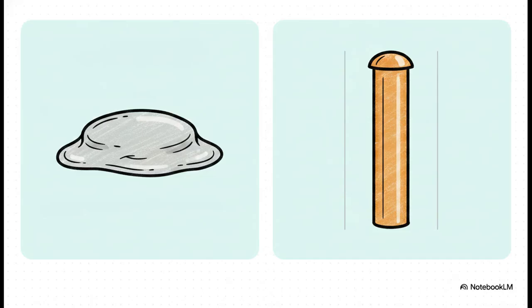To fix this, engineers execute a brilliant structural upgrade. They swap out squishy, fully melting traditional solder bumps for rigid copper pillar bumps. These copper posts are the real heroes here because they don't melt during reflow. They maintain a strict, rigid standoff height, entirely preventing that lateral solder collapse. And that is absolutely vital for ultrafine pitches under 80 micrometers.